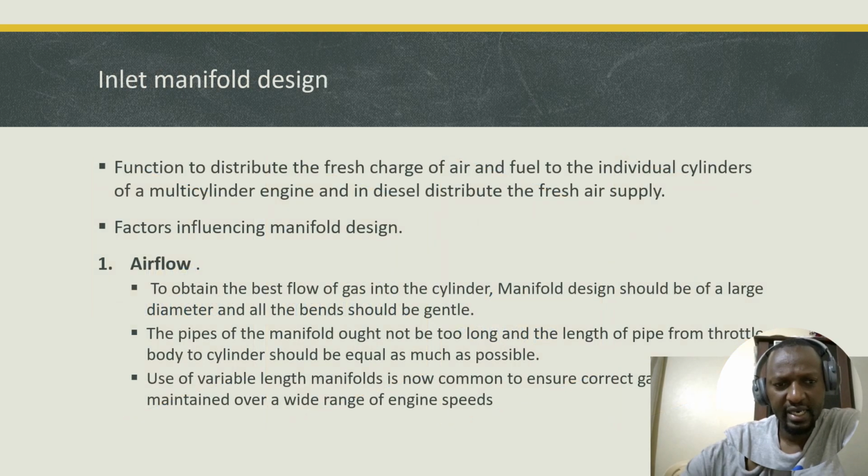So as far as the inlet manifold design is concerned, its function is to distribute the fresh charge of air and fuel to the individual cylinders of a multi-cylinder engine, and in diesel engines we only distribute the fresh air supply. So it is very important that the distribution pipes be of equal length so that we treat each cylinder equally and give it a balanced charge to make sure that they all have the chance to produce the same power.